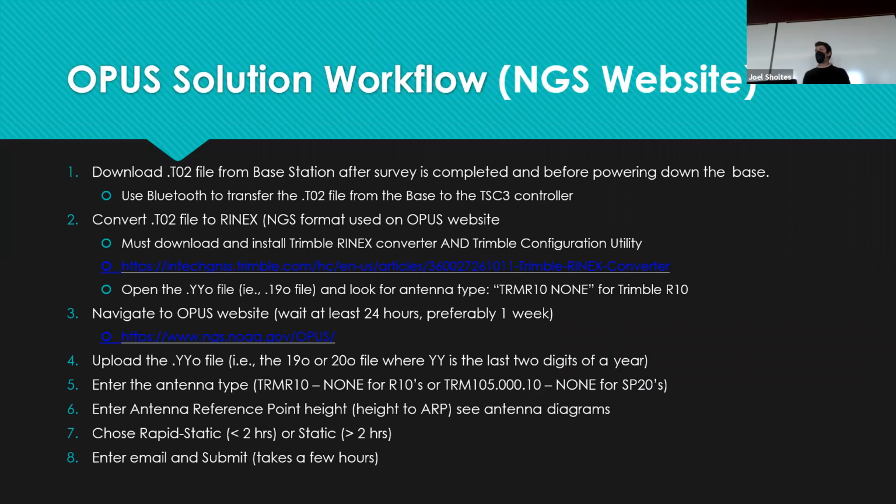The correction will be on the order of meters because your original base station XYZ was super rough, plus or minus 2 meters. So when you correct it, and we'll do it in class, it's going to snap over to the corrected location in XYZ. Your solution is going to be accurate to plus or minus centimeters, like 1 to 2 centimeters, but it's going to move your really rough point over quite a bit.